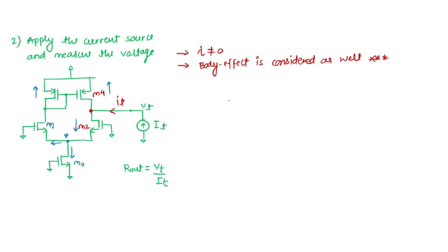I will say the looking up impedance R up from the source of M1 is much lesser than this R down from the drain of M0.